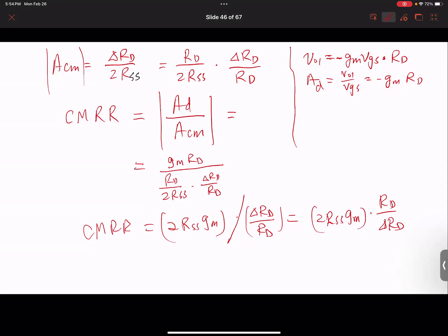You see? That's a common mode input because they're the same noise. You pick up the same input noise, same frequency, same amplitude. They come to your input. So if your common mode rejection ratio is high, then noise is canceled. At your output, you don't see anything. But if your common mode rejection ratio is small, this noise gets amplified, and you see it at your output.